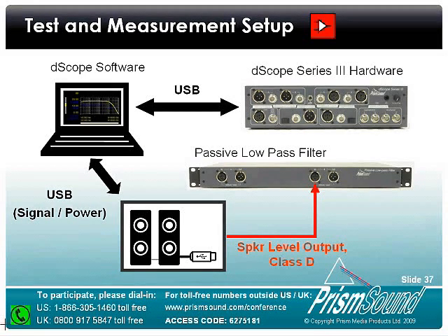Now, this audio test system is designed to measure signals up to about 100 kilohertz, and that out-of-band switching noise is not something that we actually want to enter the test system. It can potentially cause issues with the amplitude ranging circuit at the front end of any audio test instruments. So it's standard protocol to offer a passive low-pass filter solution, a calibrated low-pass filter that allows us to remove the high-frequency switching transients that may give us difficulties with our measurements otherwise. So I've connected the low-pass filter in series with the output from the terminals of the power amplifier. So once again, I have probed internally inside this loudspeaker here.